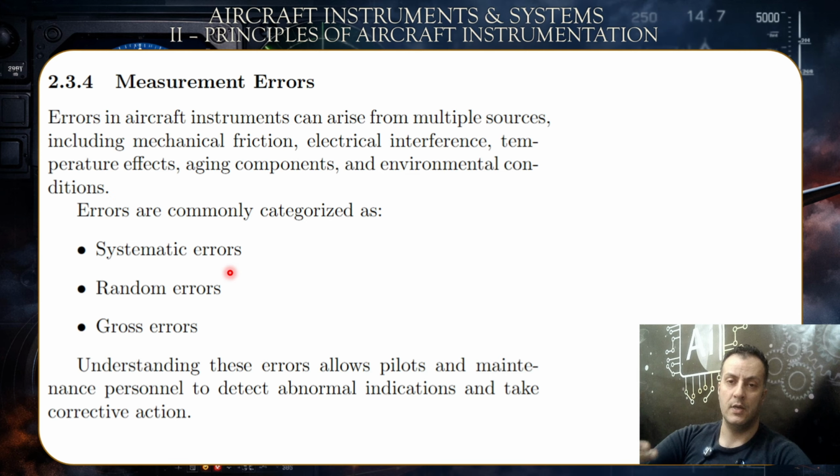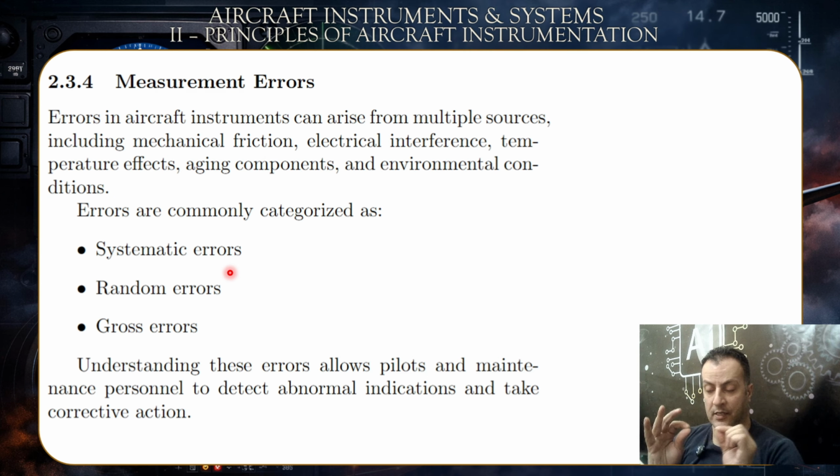It would show a false reading of the altitude, which is, by the way, the reading the autopilot depends on in order to guide the airplane when it comes to the landing. So at times it would break and show false readings of the altitude, and at times due to vibration it would go back and rejoin the circuit. So that broken circuit would get in contact again on both sides, so it would appear to be working.